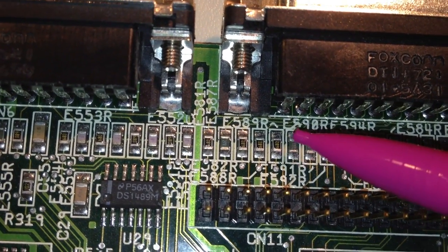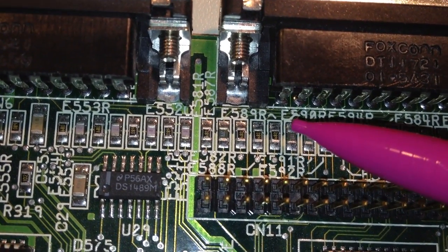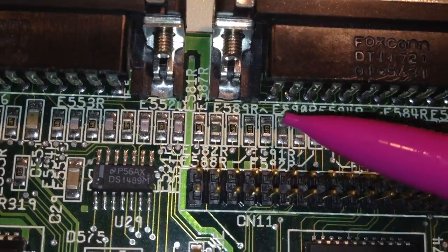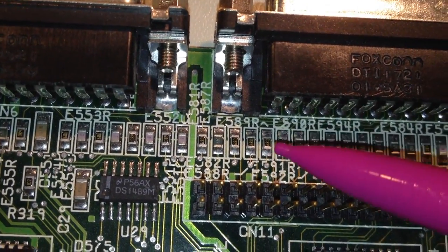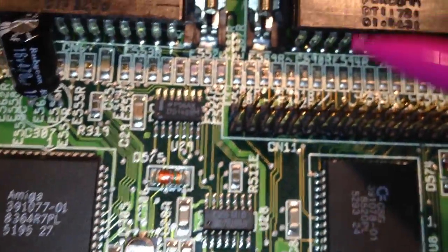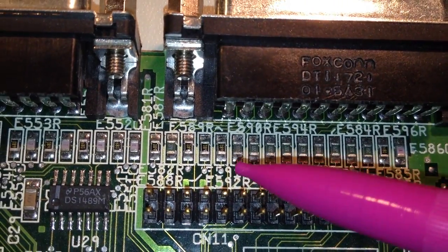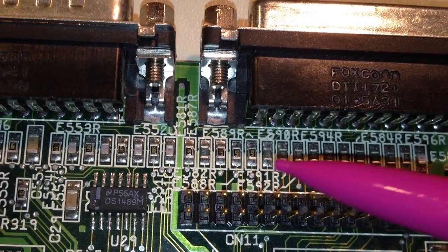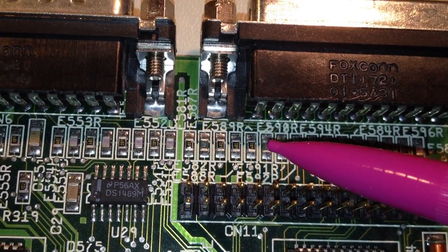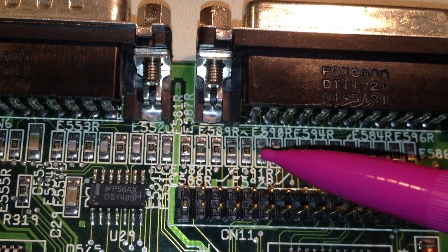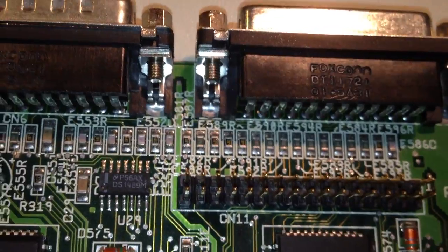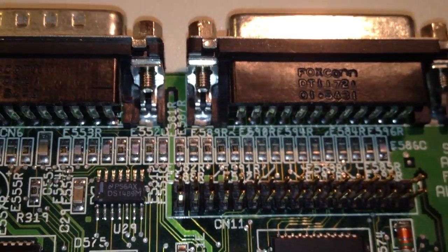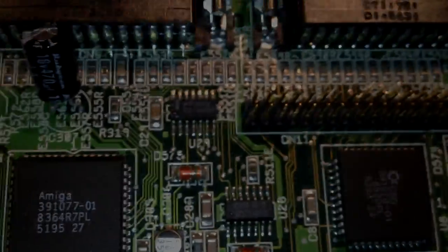You cannot jumper wire it to the upper side, that's no good, because if you do that, then you need to put a 27 ohms resistor in series on the wire. But it's better to just put it on the bottom side here, and if this resistor is the one that is causing this problem, then just replace it. So yeah, that's a few ideas.